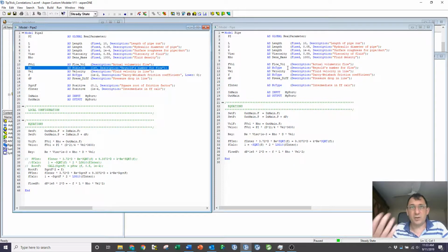No type's a useful sort of catch-all variable type, but it's got very wide bounds, and so it's challenging. Positive has a lower bound of 10 to the minus 9 and an upper bound of 10 to the 9. So that's a better starting point. In fact, 10 to the 9 might be a little bit lower. I may need to raise its upper value, but for now, I'll assume it's good enough.